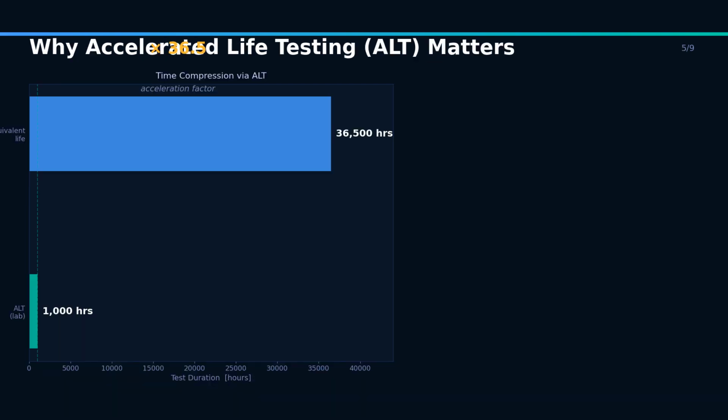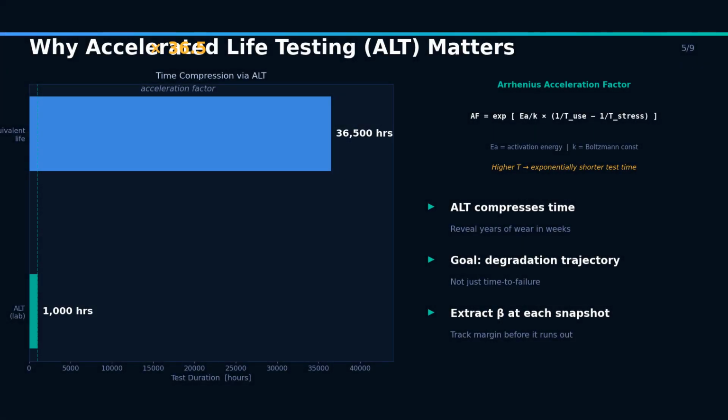In real products, both distributions evolve. Strength tends to shift left because of fatigue, wear, corrosion, creep, or microstructural damage. Often it also widens, which means unit-to-unit variability becomes more dangerous over time. Meanwhile, the stress distribution may move right as users demand more, environments become harsher, or cycling accumulates. Reliability loss is therefore not a single event. It is gradual margin erosion.